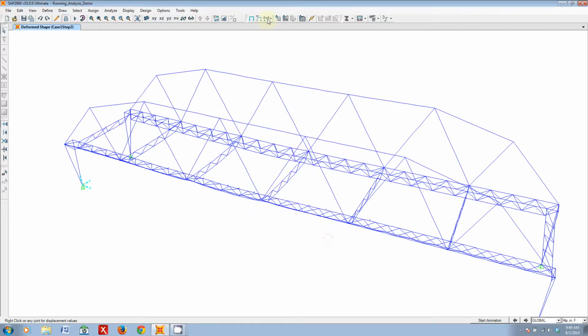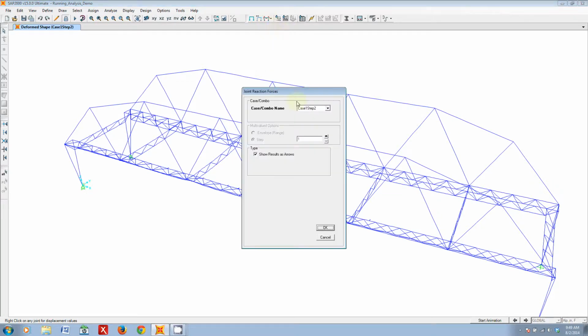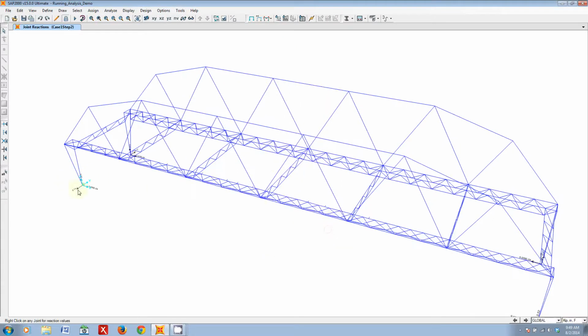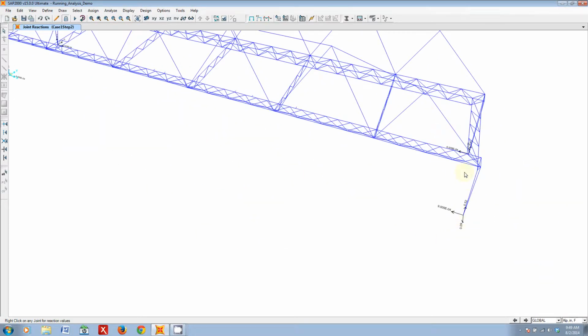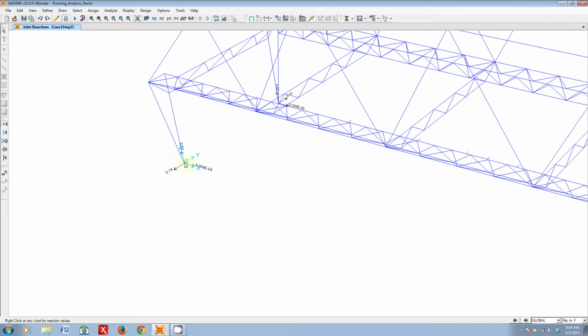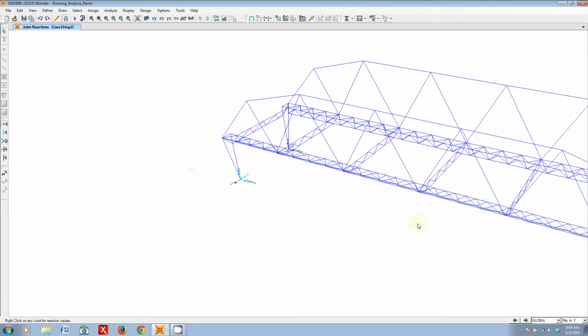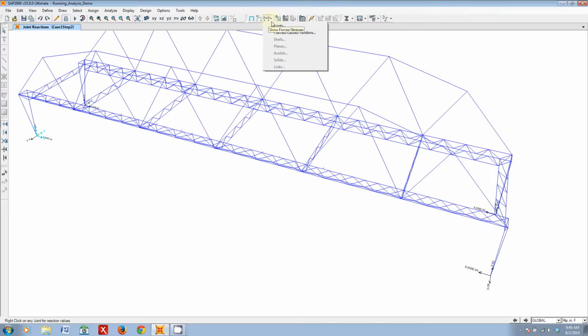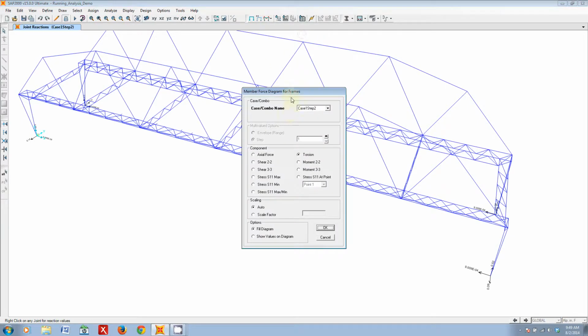So what I just did here was I went to show forces and stresses, and you can look at joints, but unfortunately this just displays the joint forces at your restraint locations, which can be useful if you're trying to determine, oh, well, are these forces big enough to have this particular support slide due to lack of frictional resistance? So that might be a good check that you might want to do. But otherwise, you'll almost always want to go to show forces, frames, cables, and tendons.